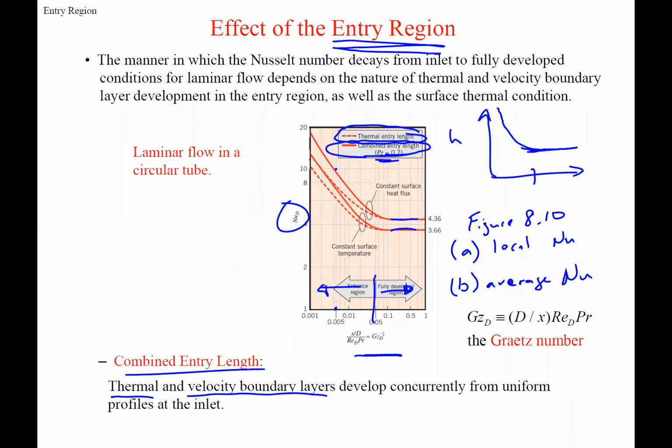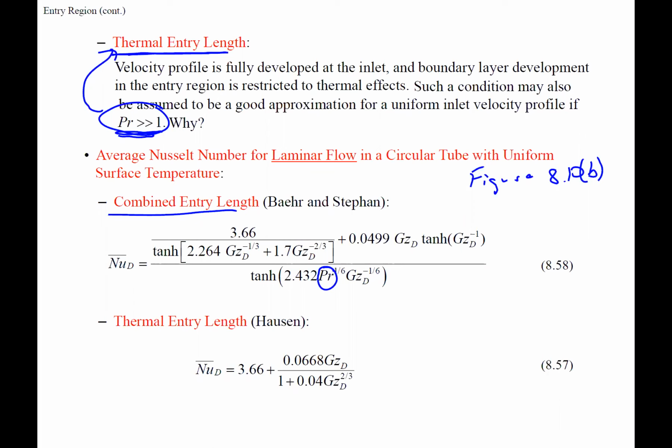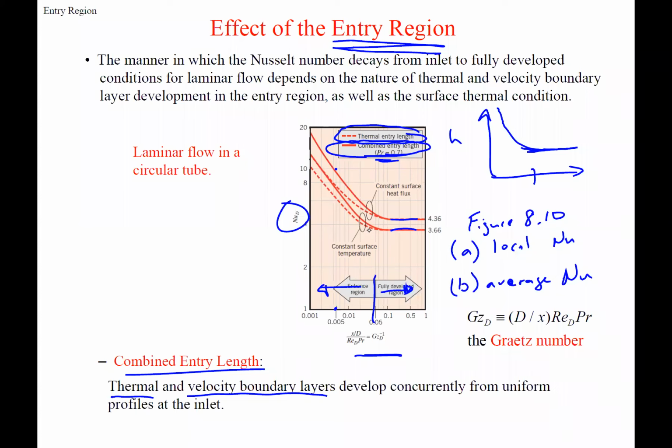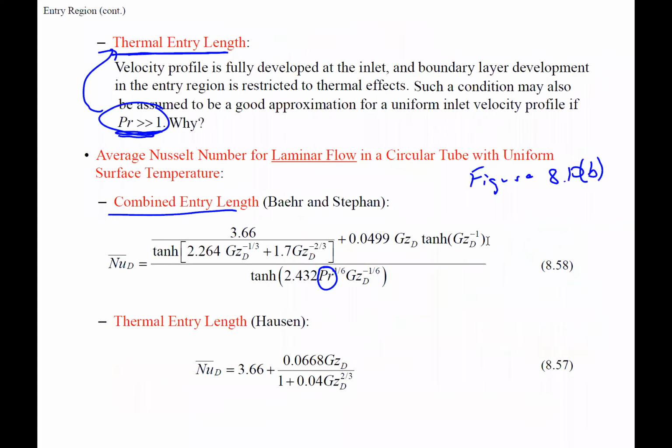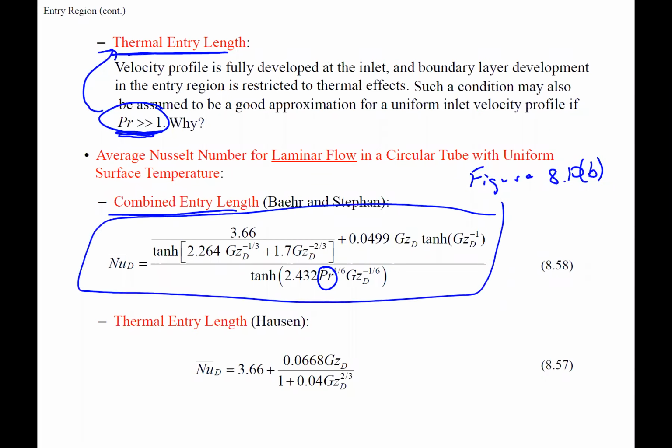Well, here's combined, but you can input for any Prandtl number. So that one just showed it for 0.7, which is, kind of, you can use this solid line in this plot for air, because air is right around 0.7. So we could use this figure instead, or we have this equation that works for any. This equation looks like a fun one, right? You'll be typing in your calculator forever and making a whole bunch of mistakes, right?